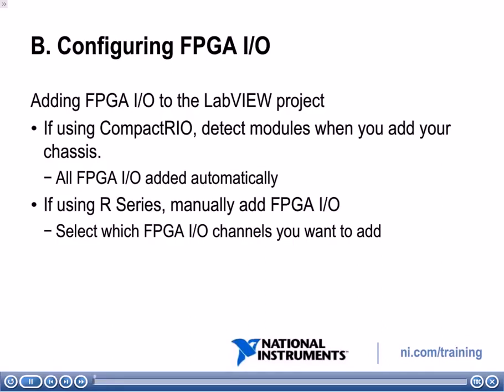In the previous section, we defined FPGA IO terminology. By the end of this module, you will be able to add FPGA IO to a LabVIEW project and access FPGA IO in an FPGA VI. Okay, so let's talk about configuring FPGA IO.